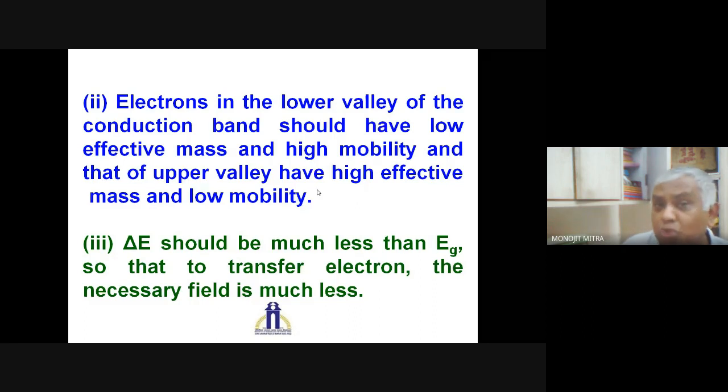But I also told you that negative resistance is a common phenomenon of all these devices, but the mechanism of how the negative resistance develops, because it is the inherent property, I am going to tell you here also. It is the inherent property of the material or of the device by which they will develop the negative resistance. But this is not like your normal resistance, which you can design considering the length or cross-sectional area of a conductor.